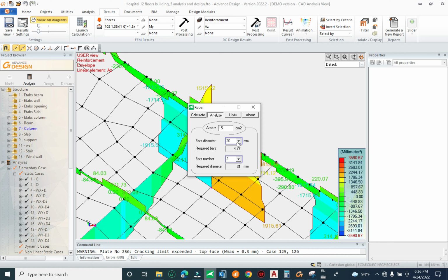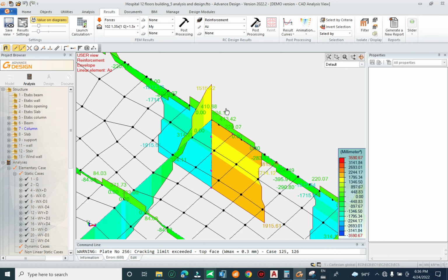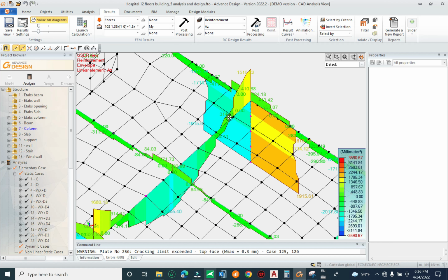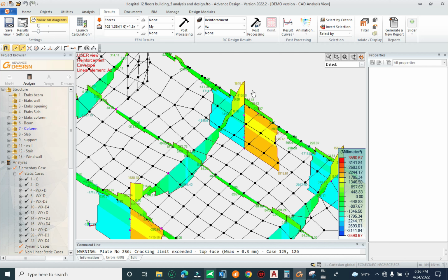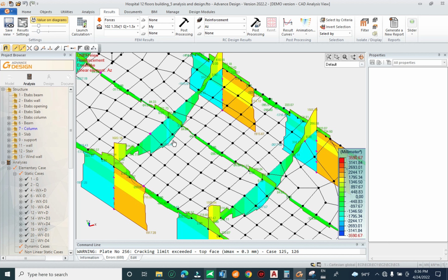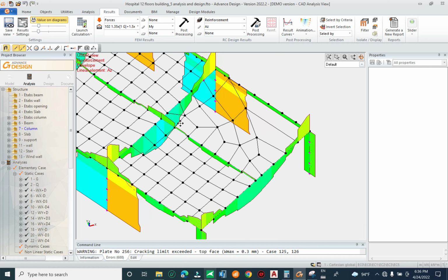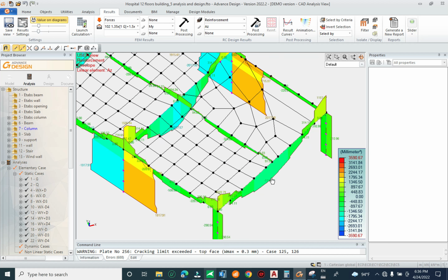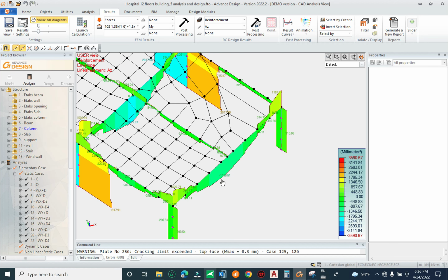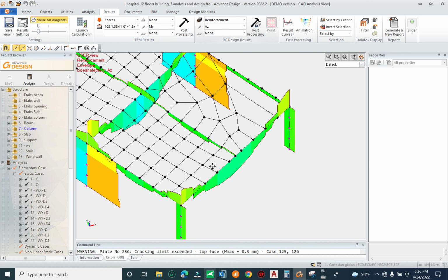and this one also needs smaller longitudinal rebar than the internal span, but this one is for the torsion rebar. See here, for the torsion rebar, the edge beam needs more rebar to resist the torsion.